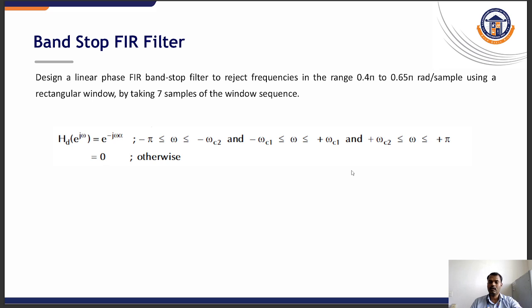Because of their non-recursive structure, FIR filters are inherently stable, and there is no possibility of an output feeding back into the system and causing it to become unstable or oscillate. Unlike IIR filters, which require careful pole placement to ensure stability, FIR is not so.